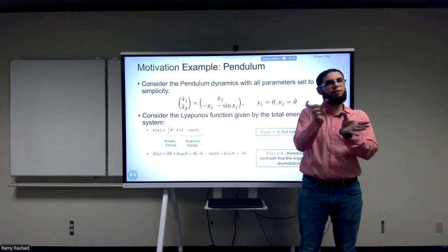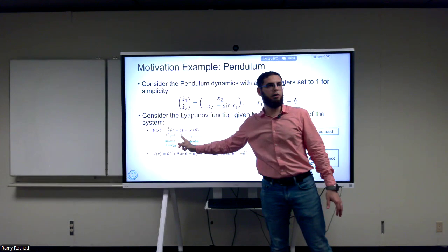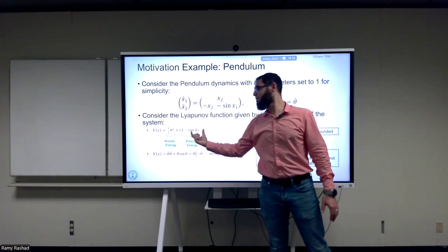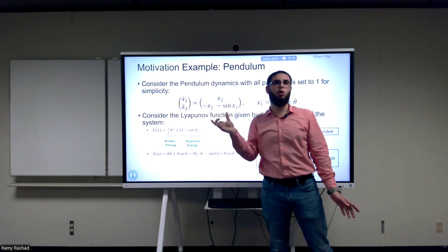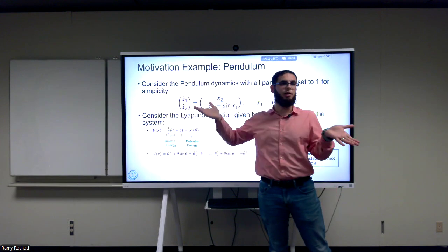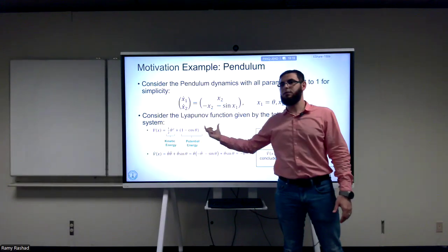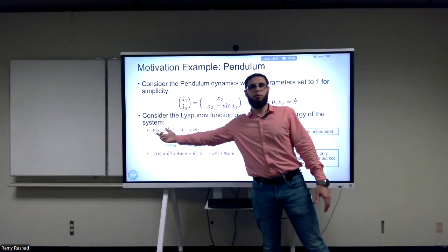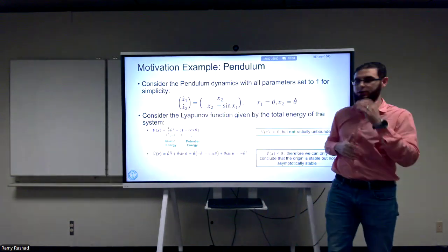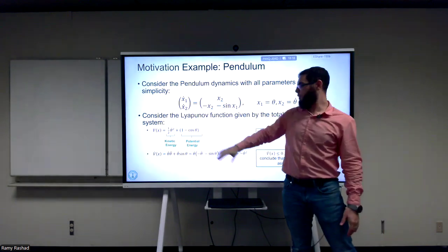I can always shift the Lyapunov function. I know that V of x star, in this case, will give me 2. So I can just add minus 2 here, and it's just a constant. When I take the differentiation, it will disappear. This is a very nice trick: we can always shift the Lyapunov function by any constant, just to make sure that we get the value to be equal to 0. In either case, let's start with this Lyapunov function.